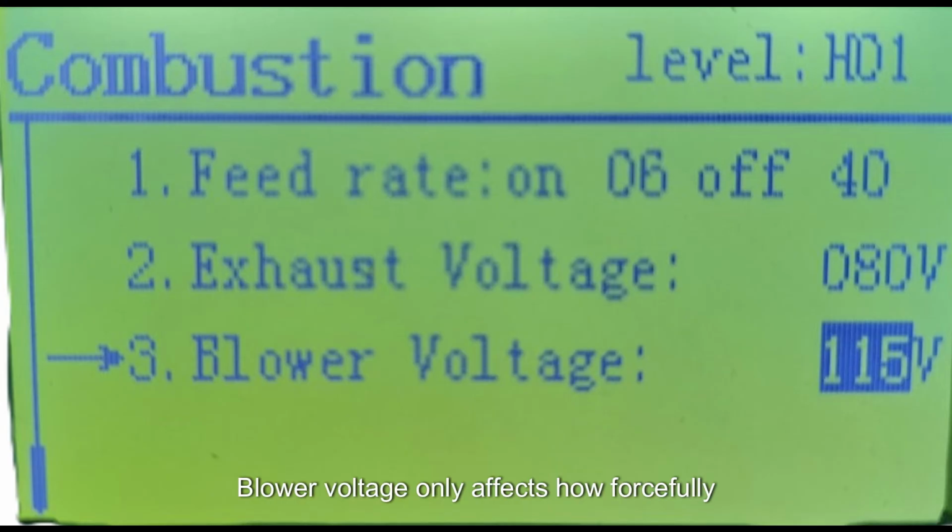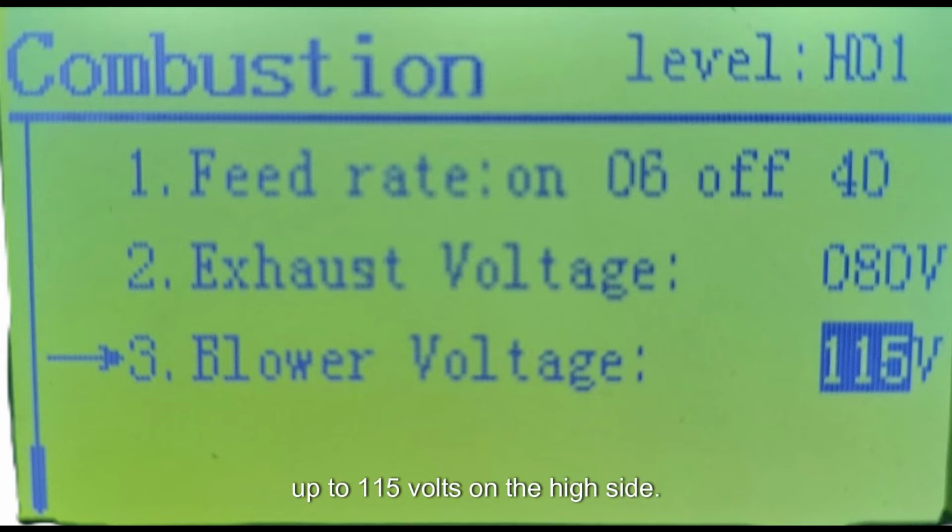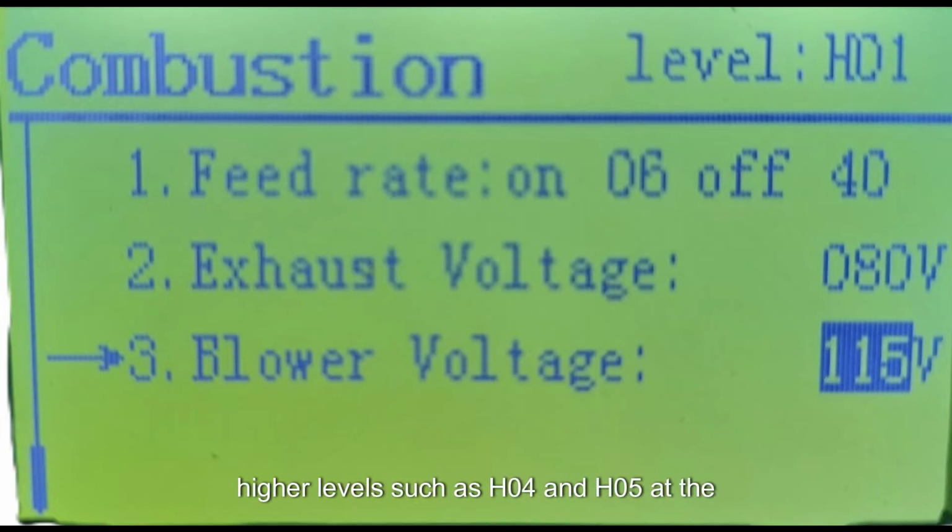Blower voltage only affects how forcefully the hot air distribution is out of the front of the unit and does not really affect the combustion or fire pattern. Like the exhaust voltage, blower voltages can be set on a range from 80 volts on the low side up to 115 volts on the high side. A good rule of thumb for altering the blower voltage is this: if the sound level is not at a pitch or frequency that is unpleasant, try to keep it as high as possible. I would recommend always keeping your higher levels, such as H4 and H5, at the maximum of 115 volts for the maximum CFM and heat output potential.